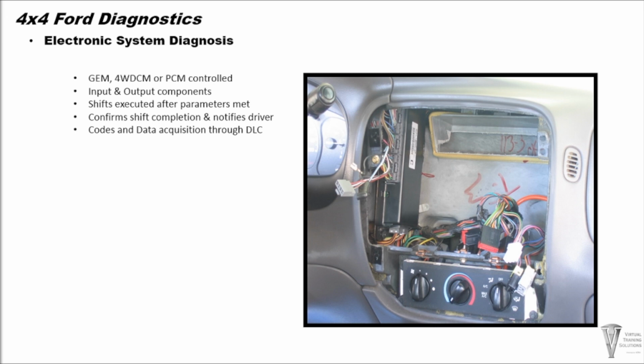Ford's 4x4 systems are controlled by the GEM module, the four-wheel drive control module, or the PCM, depending upon vehicle application. The GEM module, the four-wheel drive control module, or PCM uses various inputs and outputs to control the 4x4 system operation after all parameters are met to allow the 4x4 system to work. The GEM four-wheel drive control module, or PCM, confirms the request from the range switch change has been completed by illuminating the appropriate indicator light. Diagnostic codes and data can be retrieved by using a scan tool connected to the DLC connector.